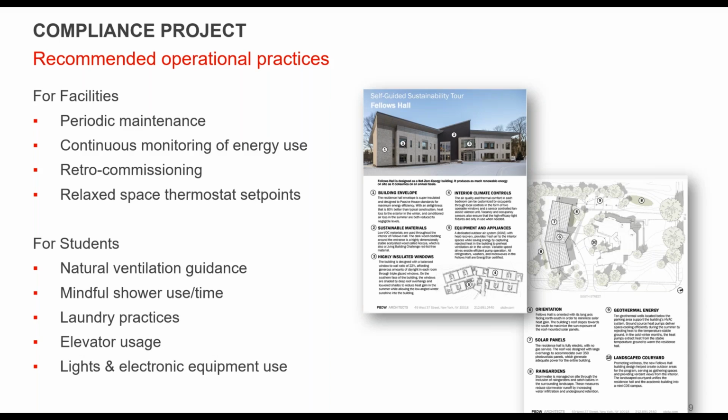We need to be monitoring energy use continually. So if we see any significant changes in that, even some sliding in that, we can look to see what's happening. Retro-commissioning, regularly checking that all equipment is working as planned, and relaxing space thermostat set points a bit so that people that want something that's maybe not quite as controlled can do that.